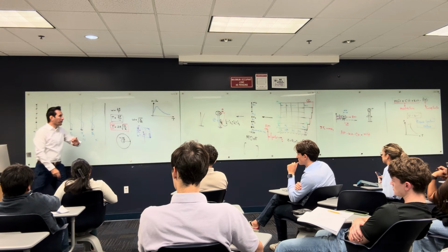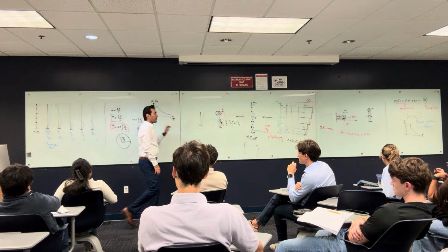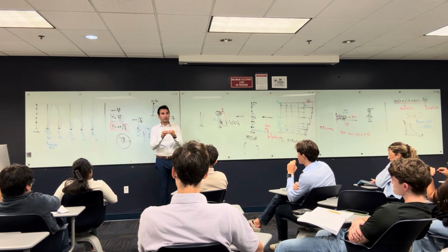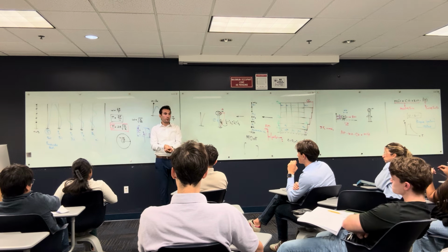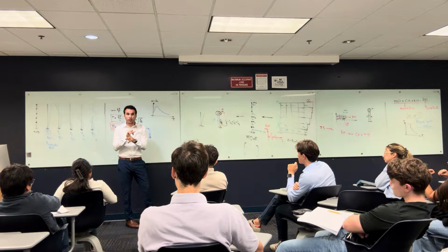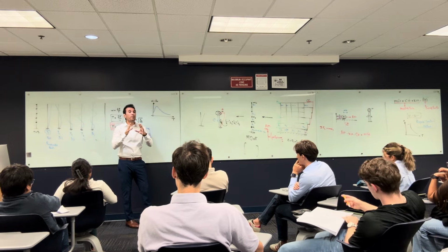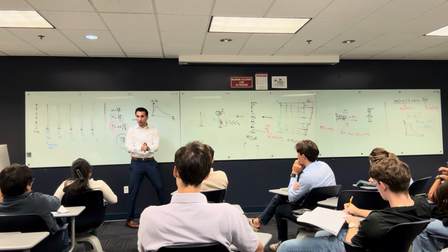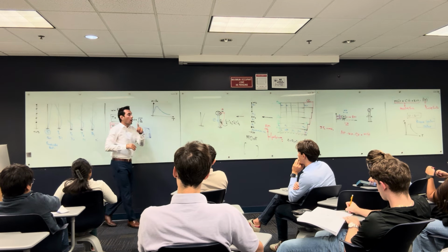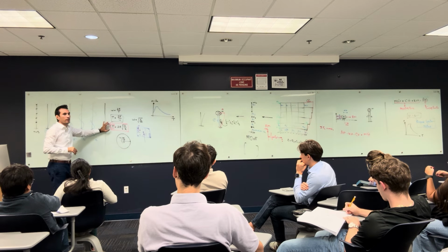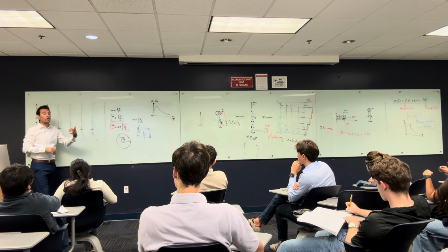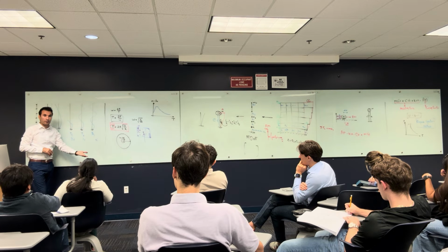So I'm going to continue the concept of response spectrum next time, but I want to finish this lecture with one thing. You have to understand the fundamental period of the structure is like the fingerprint of your structure. It is attached to the structure. It doesn't depend on the load applied on the structure. It doesn't depend on the earthquake. It depends on the structure itself and its parameters. Okay? It doesn't matter whether the earthquake is big or small. Every structure has its own fundamental period. It depends on its mass, stiffness, and the potential of this structure to damp the force of the earthquake.